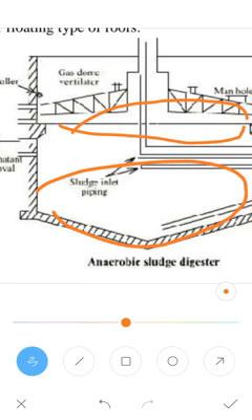After the standard rate sludge digesters, some removal of gases can be done, but the high rate digestion gives a high amount of gas recovery, and the sludge rate will be more in the high rate sludge digesters, mainly due to separating the digested solids from the supernatant liquor.